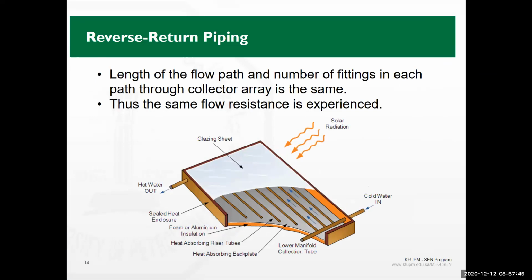This is a cutaway view of a flat plate collector. And you may see here as the solar energy passes, it penetrates through the glass. The glass has a transmissivity. It falls down. This gray thing, basically, should be a black surface, which is the absorber. It gets heated. And then we have tubes that are mainly made of copper, because copper has a very high thermal conductivity, that are connected through a header.